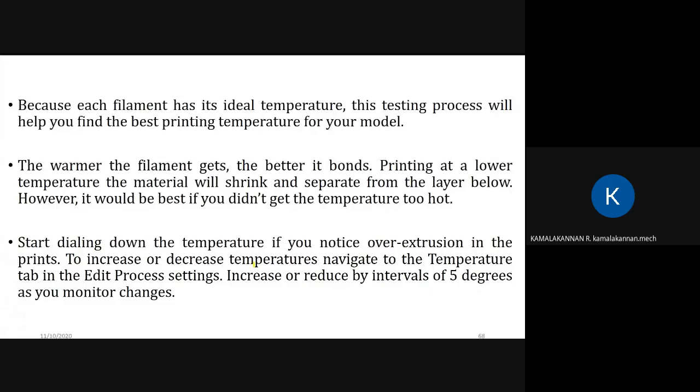Because each filament has its ideal temperature, this testing process will help you find the best printing temperature for your model. As I said earlier, the warmer the filament gets, the better it bonds. Of course, warmer increases the chance of bonding. If it is colder, the chance is less, so it will create a problem. Even if it is too hot, it would also create problems. So adjusting to the proper temperature is important.